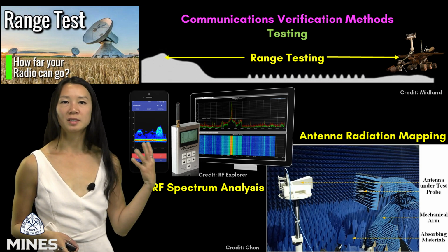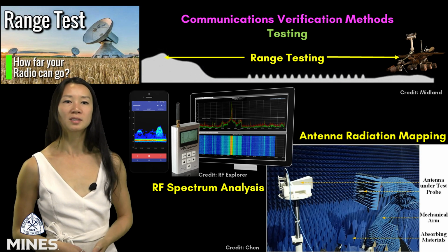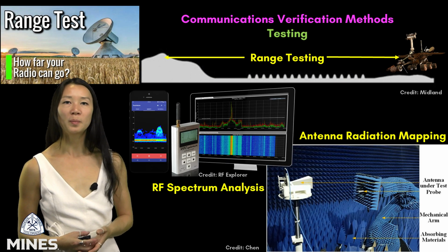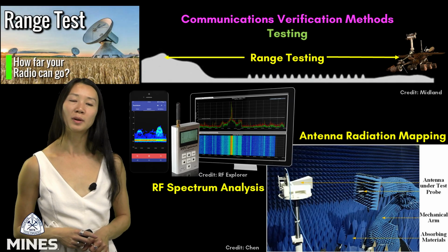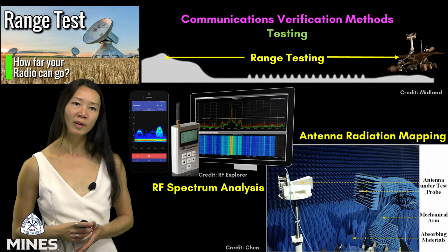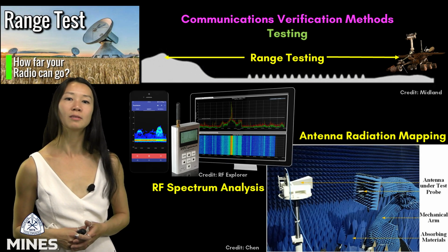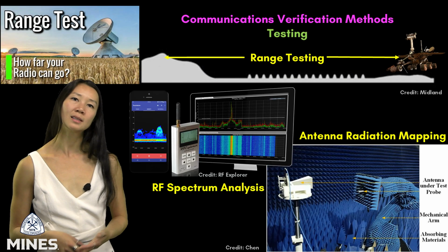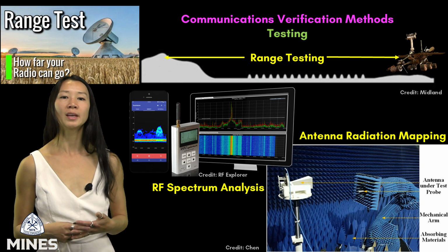And behind just this subset of testing are other tests that support system verification, like loopback and end-to-end testing to confirm the whole signal path works, protocol testing to make sure packets are well formed and timing is correct, and eventually environmental testing like thermal vacuum or vibration to simulate launch and space conditions and see if your comm system holds up. The core idea of testing is to analyze it, simulate it, and then test it rigorously so your communication subsystem is ready for flight.